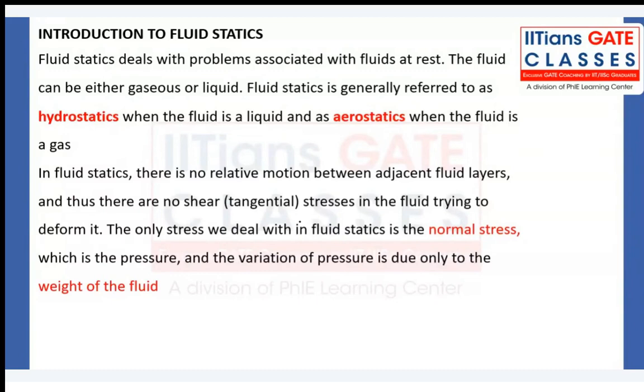When the fluid is under rest condition, there will not be any relative motion. When there is no relative motion, there will not be any tangential stresses in the fluid element trying to deform it. The only stress we deal with in fluid statics is normal stress, which is nothing but pressure. And the variation of pressure will happen only due to the weight of the fluid element.